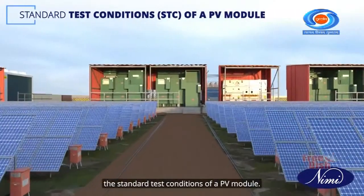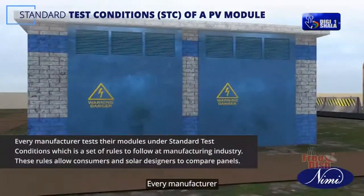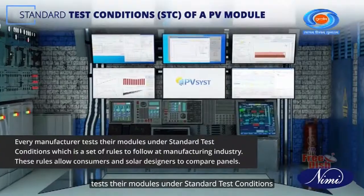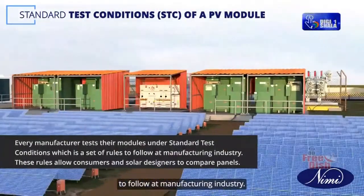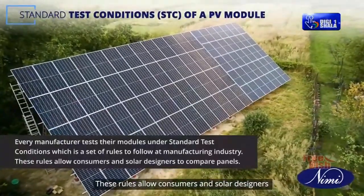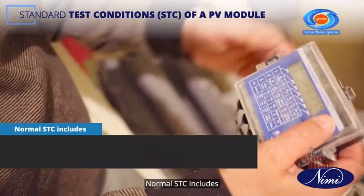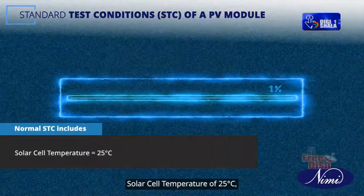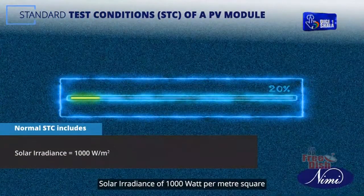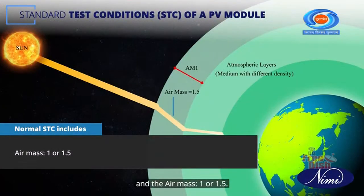Let us learn about the standard test conditions of a PV module. Every manufacturer tests their modules under standard test conditions, which is a set of rules to follow in the manufacturing industry. These rules allow consumers and solar designers to compare panels. Normal STC includes a solar cell temperature of 25 degrees Celsius, solar irradiance of 1000 watt per square meter, and an air mass of 1 or 1.5.